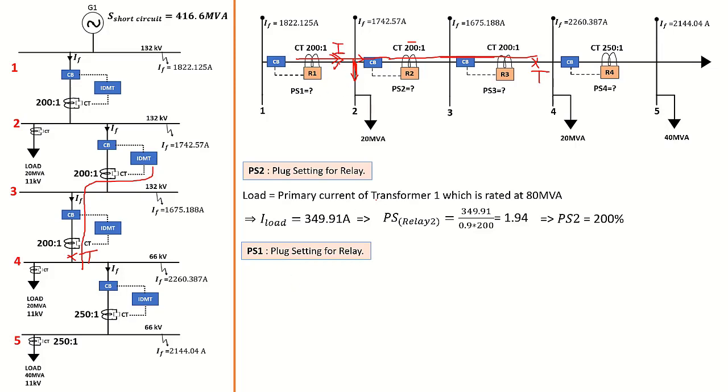That must be something around 400 amps of current, because it needs to split, one going down there, the other going this way. So in that way, we're first going to calculate the load for the 20 MVA load attached to Busbar 2. Okay. And then we're going to add it plus a primary current of transformer 1. So that will mean the load for our Busbar 2 with a 20 MVA load with 132 kilovolt, because the Busbar here is 132 at that point there.